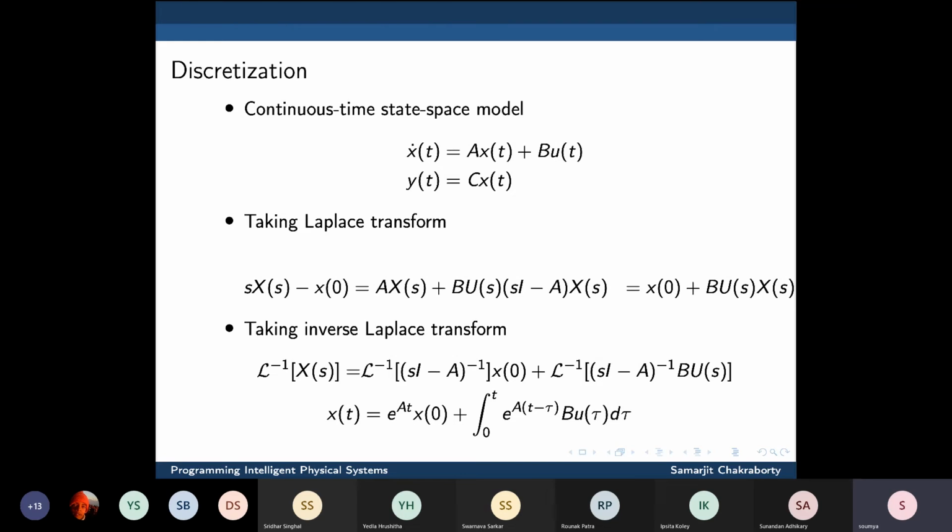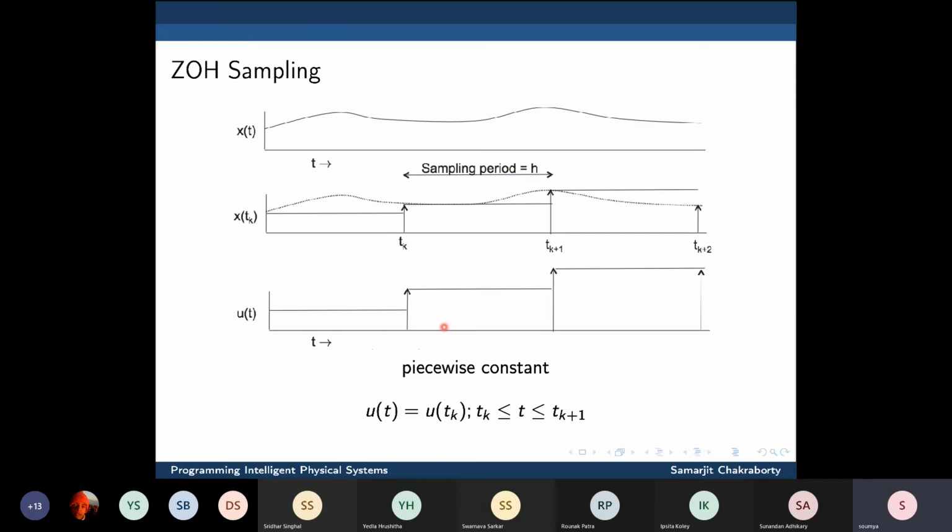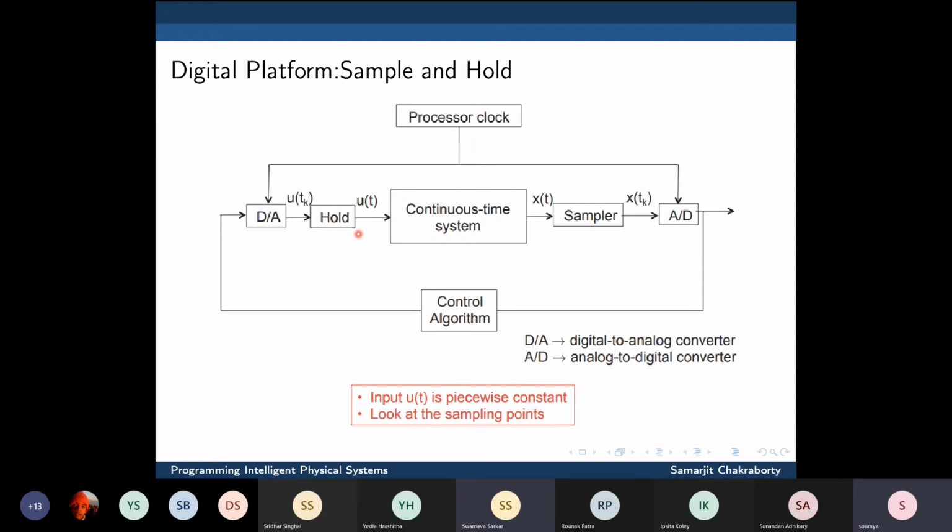Now observe one very important thing from the zero order hold. When we are doing a zero order hold, my value of u doesn't change over the interval. Am I correct? Yes, sir. Because of what? It is always being updated at the sampling period end, right? It is calculated here, then converted to an analog value.